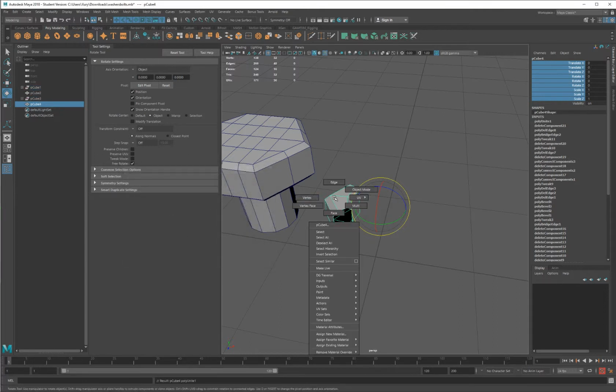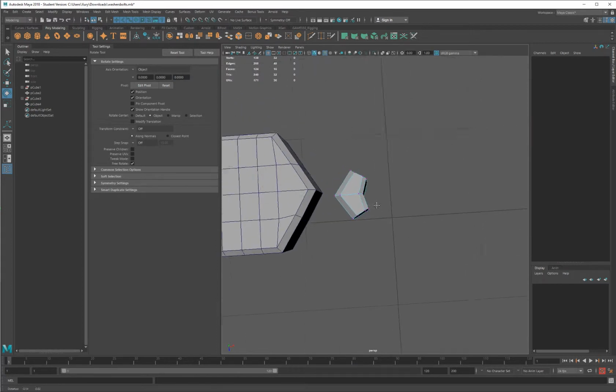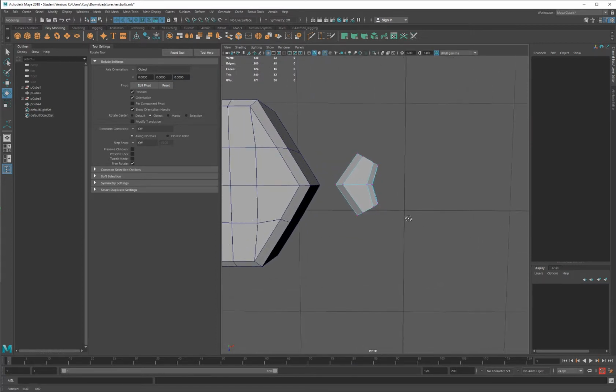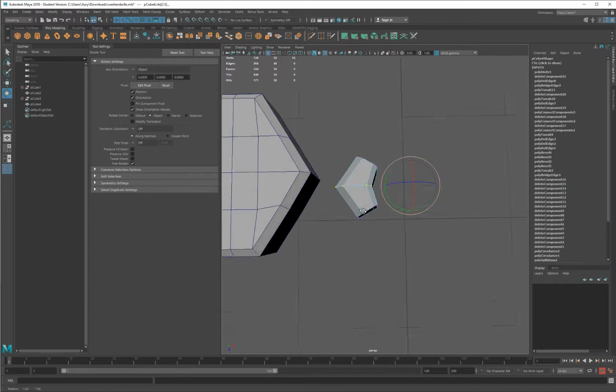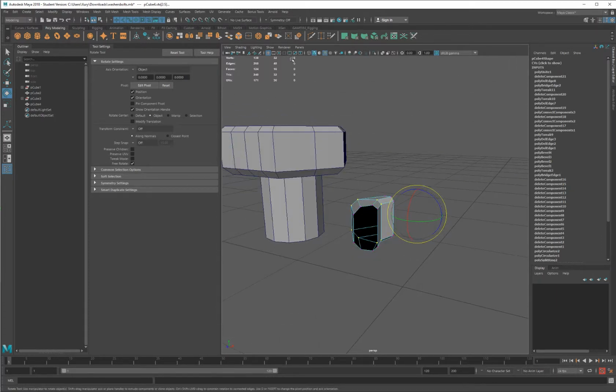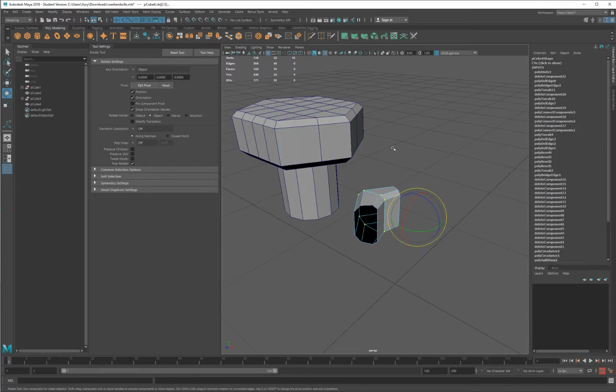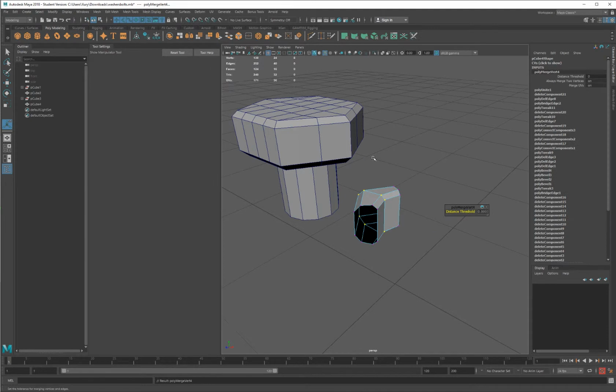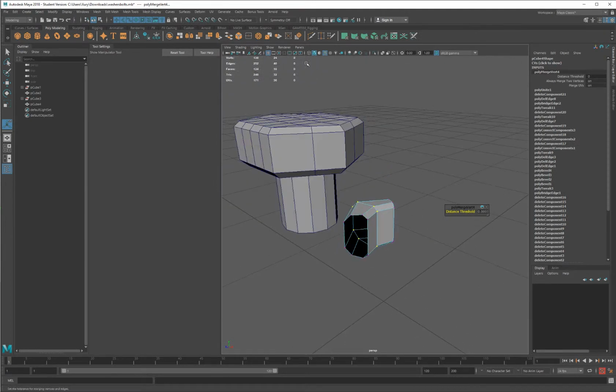They've been merged together. Go into vertex mode. Even though the objects were merged, we still have leftover verts. So I'm just going to box select over those, and we should have 1, 2, 3, 4, 5, 6, 7, 8. So we'll probably see 16. There it is. It says 16 as I suspected. So we have duplicates there. So I'm just going to merge vertices right there, and we end up with 8, just like what we should have.